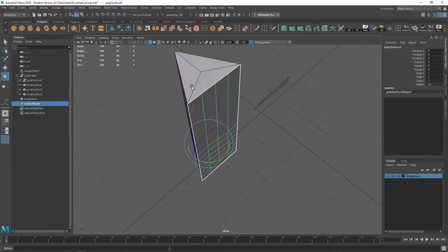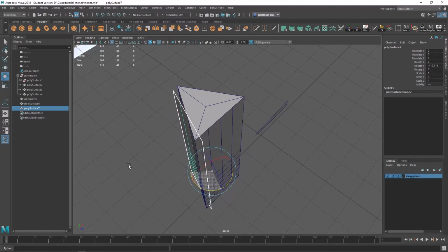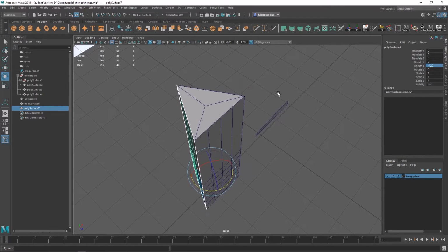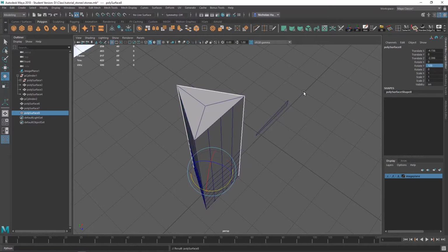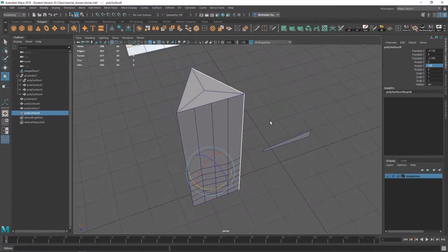That's what we want. So I'm going to Control D to duplicate. Gonna wiggle it to try and rotate it 60 degrees, I think it is. No, it's gonna be 120. But over here it's, you know, minus 119. We got close. We'll just type in minus 120 here. Hit enter. Make sure you're no longer cursored in there, so I'll just usually wiggle my camera. And then I'm going to do Shift D for shift duplicate, and it'll automatically pop over with that same transform we just did. So now we have 3.